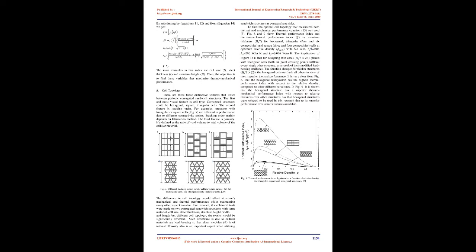D. In-plane shear modulus. Fig 3 shows a hexagonal honeycomb, by far the commonest kind. The in-plane stiffnesses and strengths, that is, those in the plane, are the lowest because stresses in this plane make the cell walls bend. The out-of-plane stiffnesses and strengths, those in the third direction, are much larger because they require the axial extension or compression of the cell walls. The direction of loading in honeycomb structures will affect its mechanical properties. The relative density and cell geometry are the main factors affecting the in-plane properties.